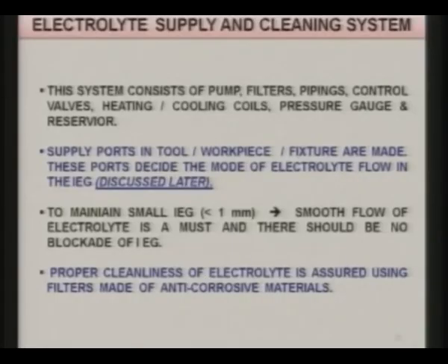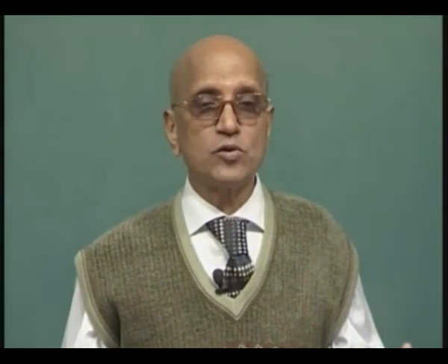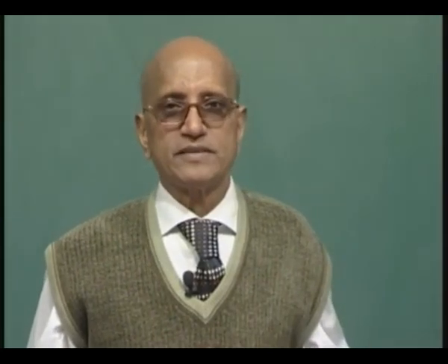Proper cleanliness of electrolyte is assured using filters made of anti-corrosive materials. Whatever filters you are using, they should be of anti-corrosive material, otherwise they themselves will corrode, and the corroded particles which go along with the electrolyte will block the passage between the tool and the workpiece in the inter-electrode gap or machining region.